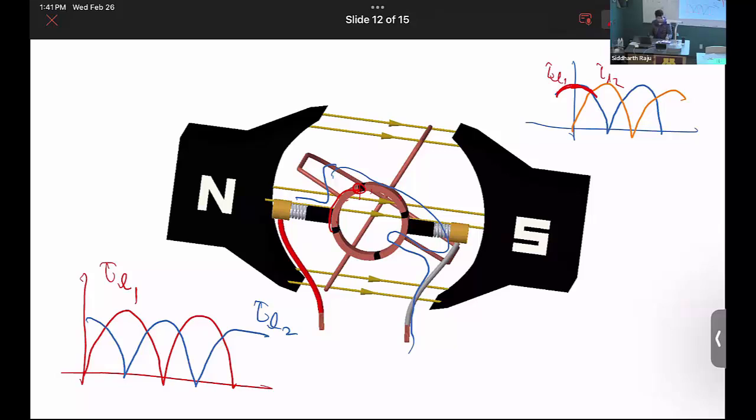Right? And then current is going to go into the second conductor, and the first conductor is going to be disconnected from the power supply. It's not going to have any current. So the torque is now only going to be produced by the second set of conductor. So we then jump on to the torque produced by the second set of conductor. And then again back, it will be the first set of conductor again, and then the second set of conductor. So we'll be riding the top wave of the torque alone without ever going to the lower part, right? So everybody clear on this?